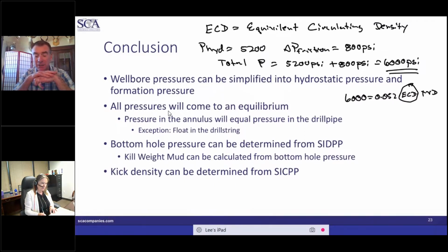So again, it's basically pit gains. Now, if you are in a managed pressure drilling situation, you should be able to determine the volume of the kick exactly just from flow in minus flow out, where they're monitoring the returns with a Coriolis flow meter. Then we can be done exactly. But on a normal drilling operation, like most of us encounter on US land, we just look at how much is left in the pits, and there's a few tricks to that.